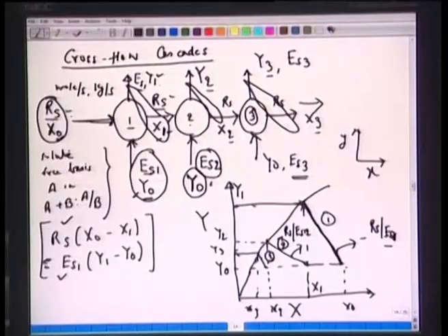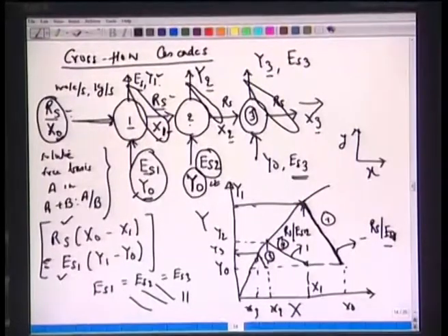All right. Then from the first stage, whatever streams come out, if we want to further purify, if we want to further separate the component A, we have to bring in the second stage or second tray, etc., where we bring it in contact with this second solvent y0. And therefore we have stage 1, stage 2, and stage 3. If the flow rates of the E phase are the same in all three, ES1 same as ES2, same as ES3, then all three lines will be parallel to each other. That's for simplicity.